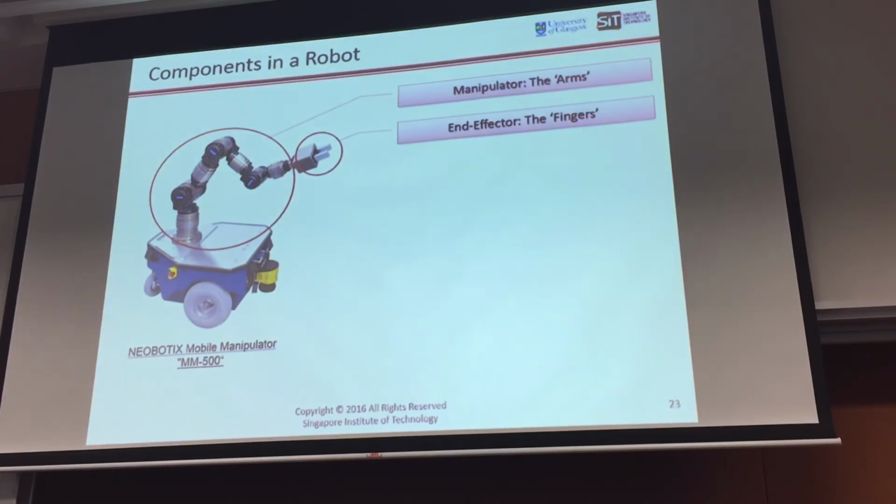so-called lifting motion. So we have different kinds of grippers, different kinds of part shapes and geometries, using different kinds of end effectors. Maybe they don't use grippers, they use vacuums to suck up some parts, to do pick and place. Actuators, the muscles, these are actually the muscles, the thing that drives the robot. If you don't have that, it doesn't work. You can have electric, hydraulic, pneumatic actuators, and a lot of other things as well, so on and so forth. There's a whole variety of things that you can use to actuate your robot.